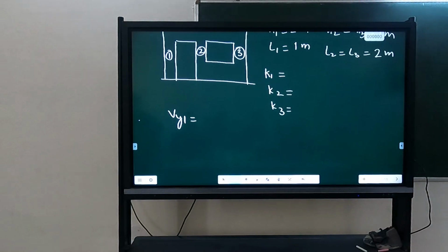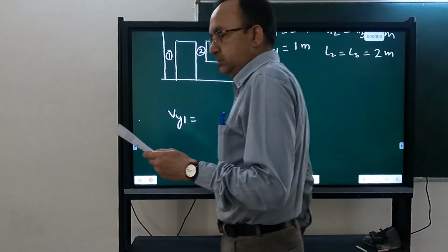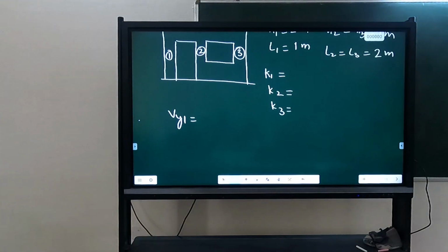the expected compressive strength is given. Okay, then the shear diagonal tension strength is given, which will control the diagonal shear. Okay, and sliding shear is also given. So you will calculate the strength in the 3 modes. Okay, and you will determine in which mode it is failing.